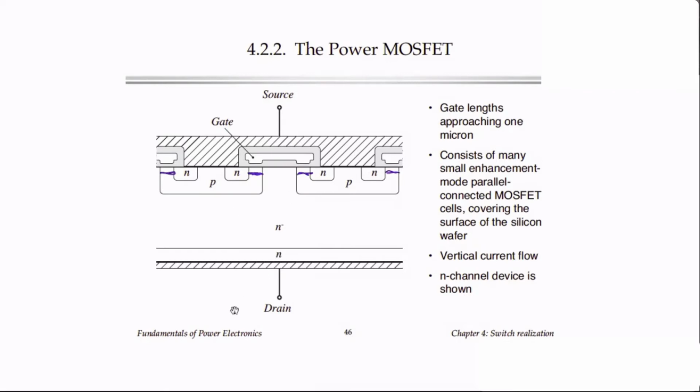When the MOSFET is turned on, the current will flow in the drain, then through the channel and out the source. That's for positive current flow. Actually, a better way to say it perhaps is we have electrons coming in from the source to the N material. When the gate is forward biased, they form an inversion layer over the channel that is effectively more N region that connects the source to the drain, and then the electrons flow this way and out the drain.